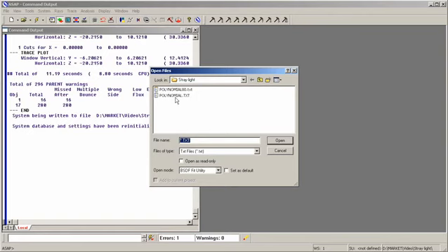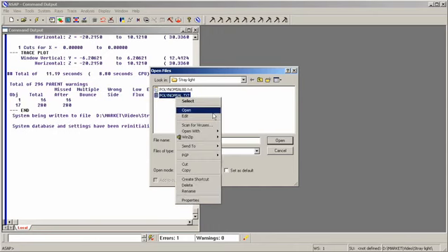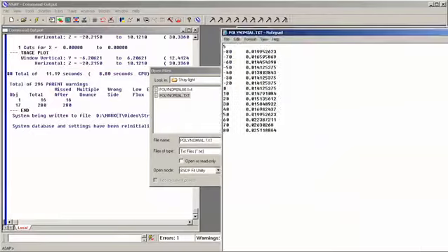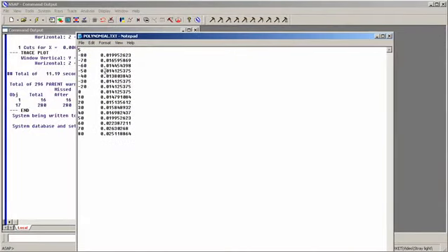Let's take a look at one of these text files before we first open it up. Here's the contents of a text file that contains BRDF data. The very first line is the angle of incidence in degrees, 5 degrees. Then comes our scatter direction relative to the direction of the reflected light. So this is minus 80 degrees. And then the BRDF data: minus 70 degrees, the BRDF at that angle, and so on and so forth.